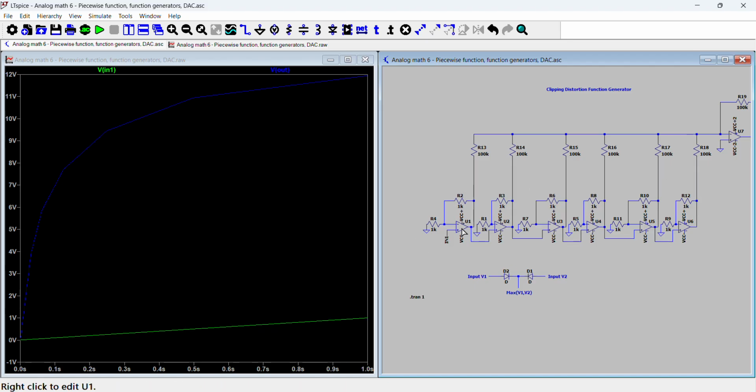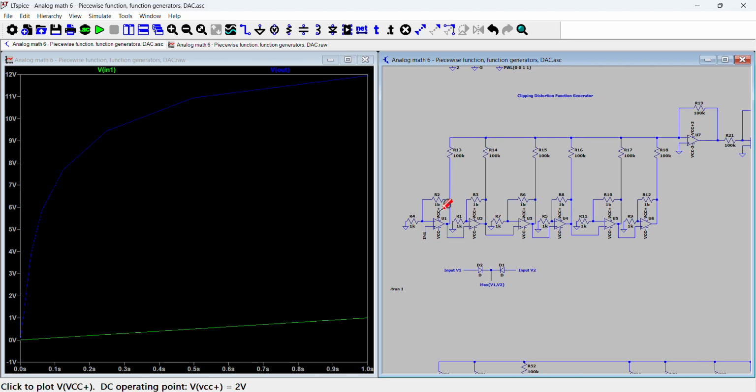So for example, this is 0.1 volts, it can output 0.1, multiplied by 2, so it can output 0.2, this one can output 0.4, 0.6, 0.8, etc. And therefore, as the voltage increases from 0 to 0.1 volts, all of these amplifiers are contributing to the voltage increase, the rate of change of the voltage. So that's why the slope is the steepest when the voltage is low.